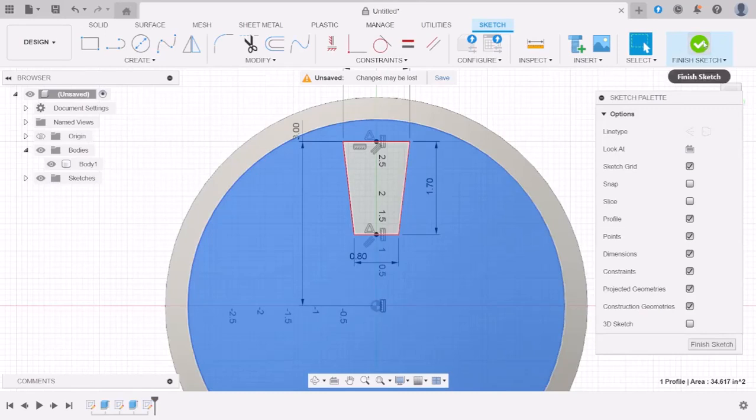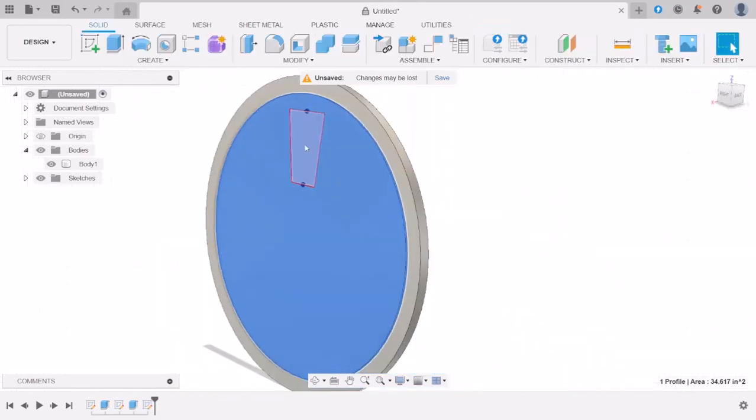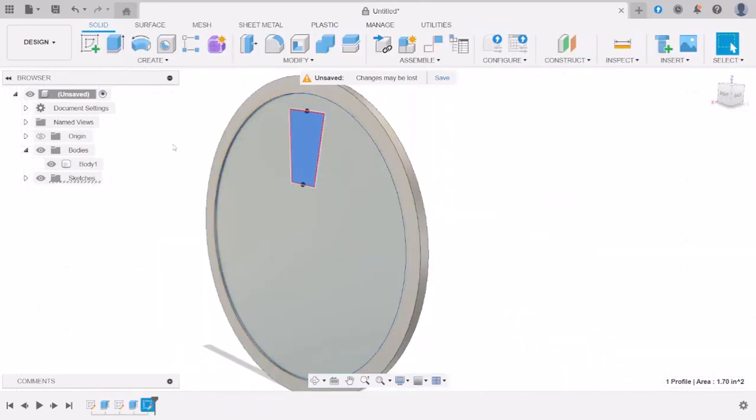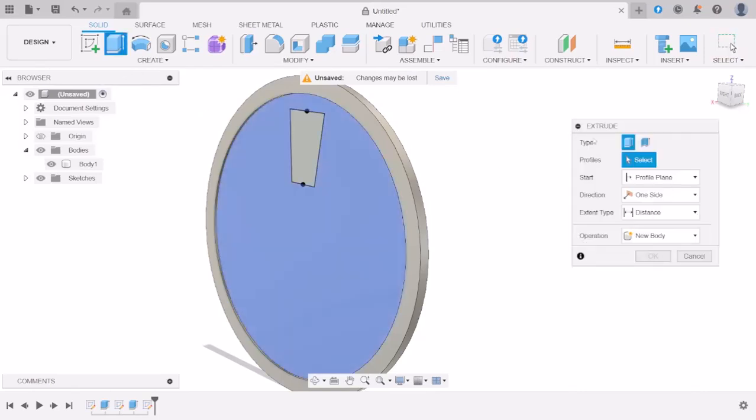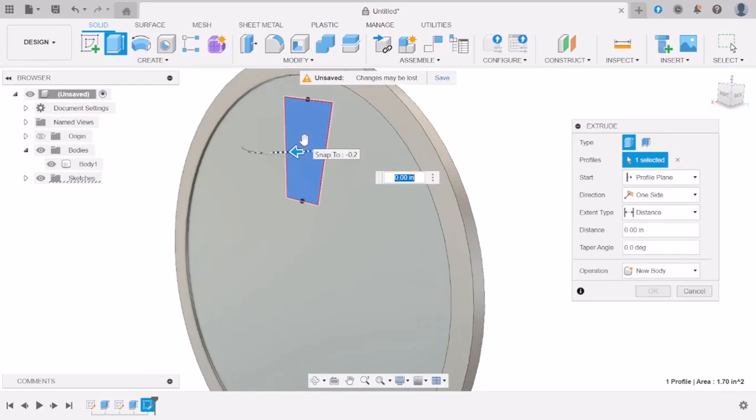I want to click on this center. I want to extrude, so I'll click on the extrude feature, then click on the profile I want to extrude. This here is a profile, this is a profile, this is a profile, but this is a sketch. While in a sense it's a profile, it's a sketch. So I'd click on that sketch and I'd extrude.